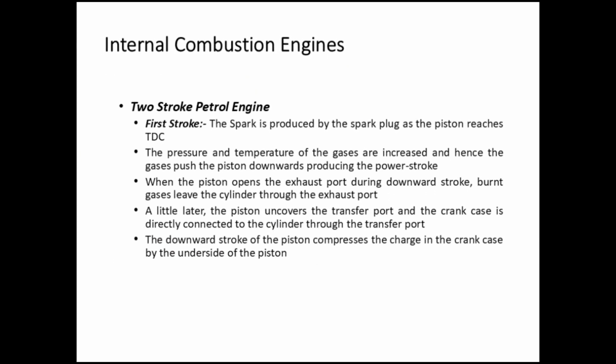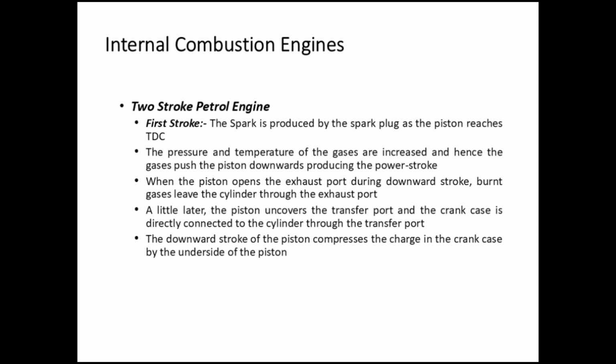Internal combustion engines. Two-stroke petrol engine. First stroke. The spark is produced by the spark plug as the piston reaches TDC. The pressure and temperature of the gases are increased and hence the gases push the piston towards producing the power stroke.